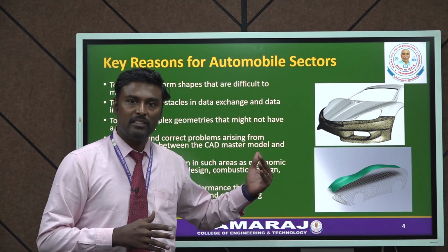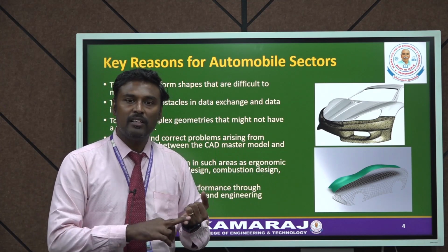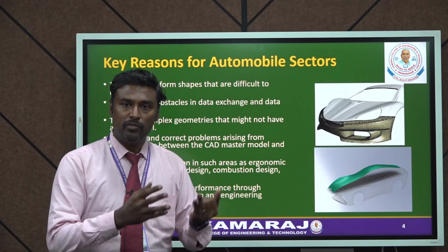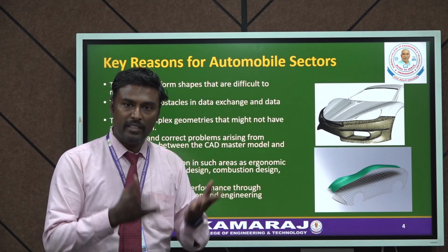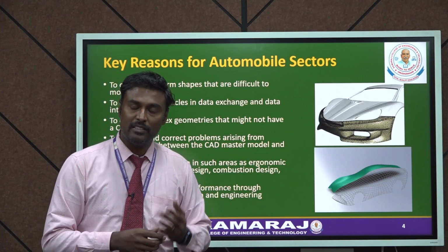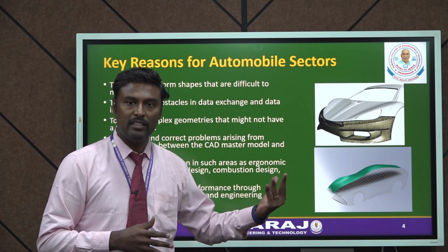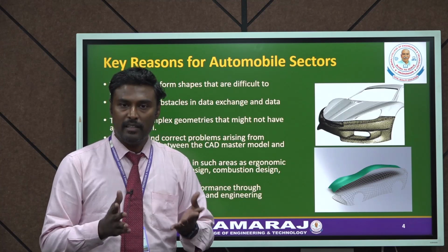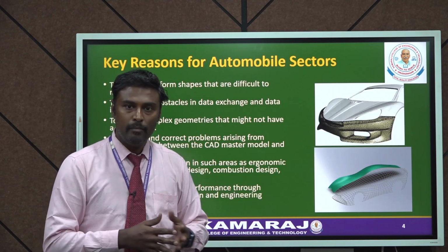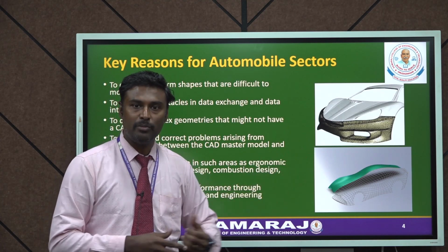All the smooth surfaces can be connected by Bezier curves or B-spline curves, and the curves will be interconnected to form surfaces, that is Bezier or B-spline surfaces, and sometimes NURBS, non-uniform rational B-splines. These surfaces may form continuities like C1, C0 continuities. Based on these continuities, some solid models have been recreated.